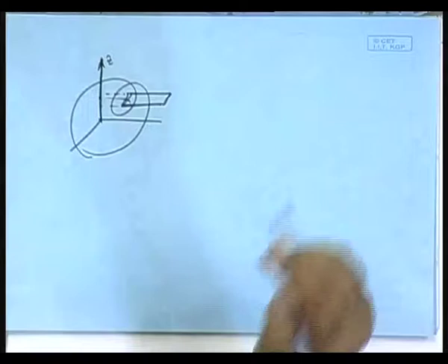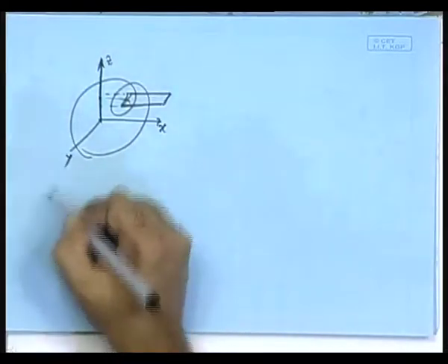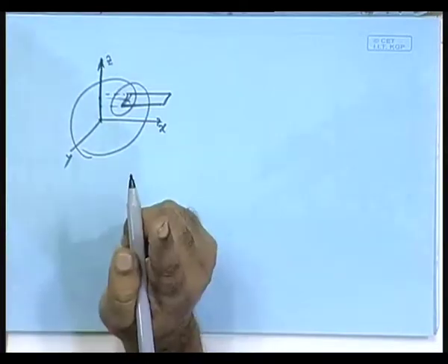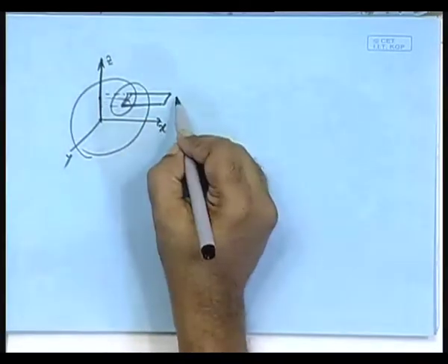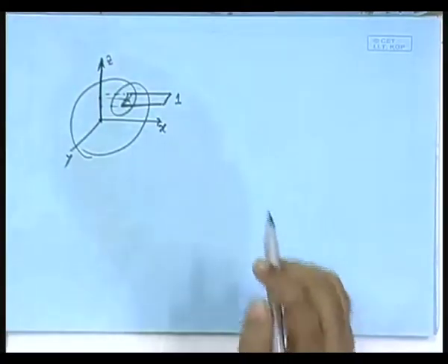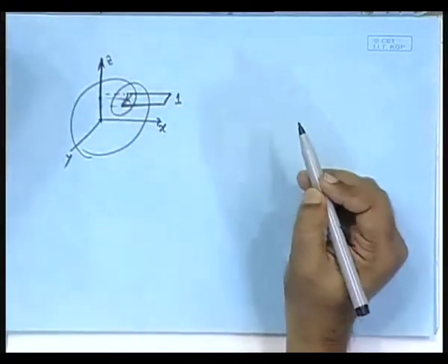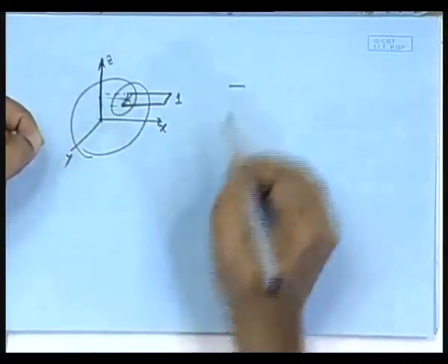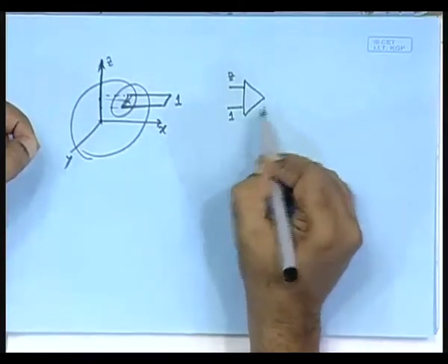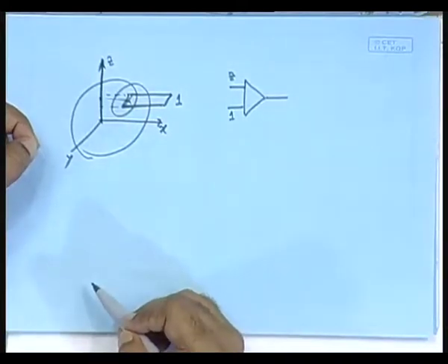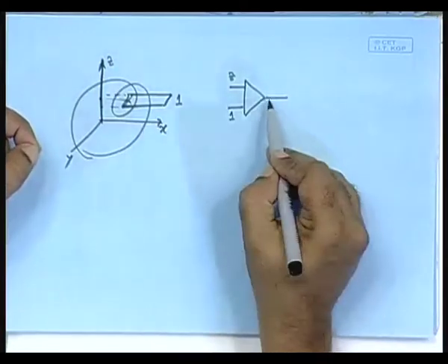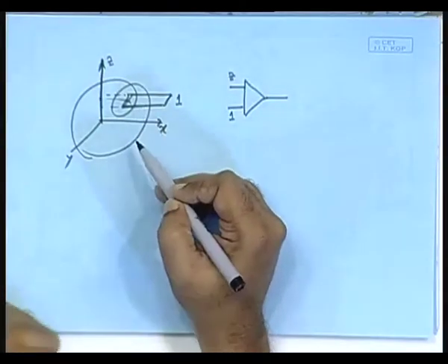You get the point? Here you have the x coordinate, here you have the y coordinate, here you have also the z coordinate, and you are placing the Poincare section such that whenever z is, say, 1, then I observe it. What does it mean? I will have to take the voltage corresponding to the z coordinate, compare it with a signal 1, and put a comparator. Whenever this comparator changes sign, you know that it has been crossed, okay.